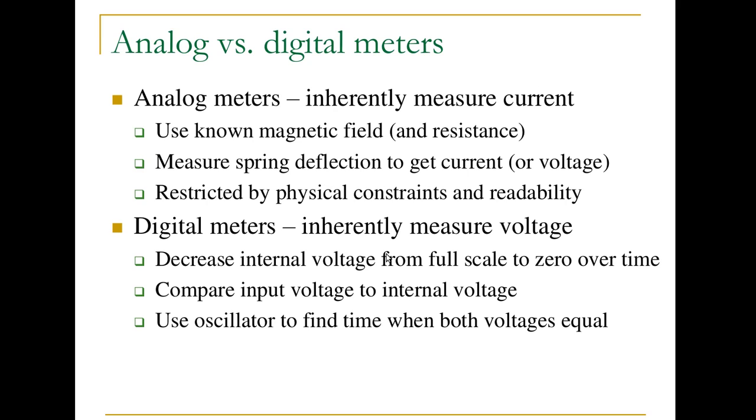What we just looked at was an example of an analog meter, and they measure current. That's where they start. And like I said, you could measure other things from that. So if you have, for example, a known resistance, you can measure voltage using the same meter.